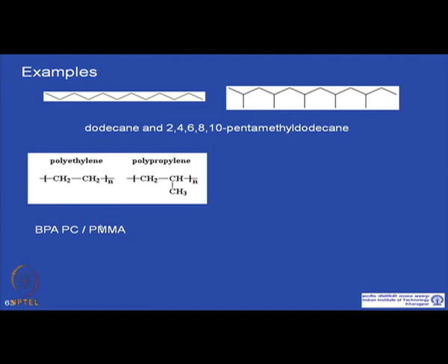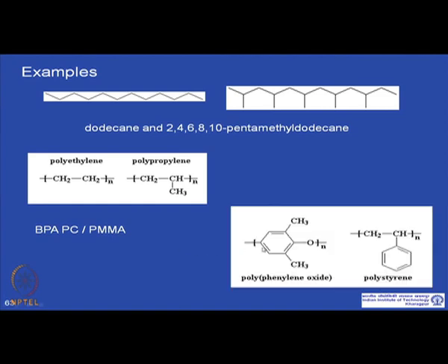So, as we increase the molecular weight, the miscibility between two polymers comes down, unless there is a specific interaction which makes the enthalpy of mixing negative, which happens here, like polyethylene oxide and polystyrene. Because of the presence of aromatic rings, they can do pi stacking interaction between them, and because of this specific interaction, their enthalpy of mixing is negative, and as a result they form a miscible blend.